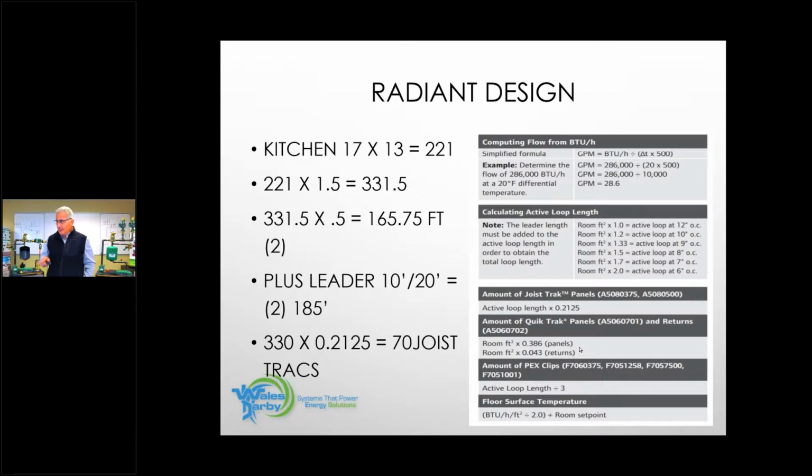Are we putting the radiant in the ceiling? In the ceiling, yeah. If you're going to do it in the ceiling, it's actually reversed. And we could do it with the joist track, but we would probably do that more with quick track. The quick track would be screwed up to the ceiling, and they would put the sheetrock up against that. And then you would put insulation on top of that. No need for a vapor barrier. You just put the insulation on top. And there, it's not going to be an R11. You're going to have probably minimum 25. You're going to be 30 or higher.